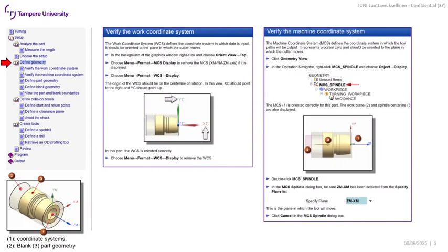This has become more and more important if you are creating your CAD model in different orientations, or for example, with the commands extrude and revolve. When we are using revolve, normally the axis is going to be automatically considered, so the software considers that one and there normally wouldn't be any problem. But if you are creating your shaft with extrude and you are taking the modification from different commands, this is something you should also pay attention to.